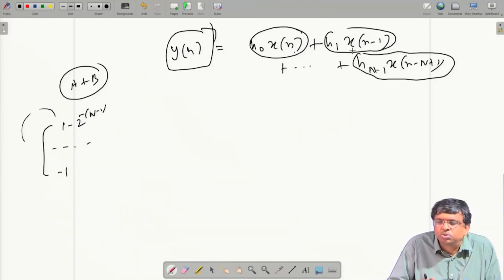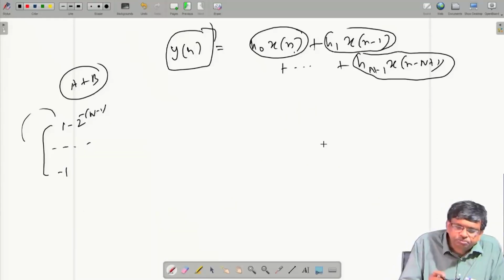This is a property of the two's complement number system, which is very useful in digital signal processing, because here you come across convolution sums where too many things will be added, or you do a transform, discrete cosine transform or DFT, where again in the summation you have too many things to be added and like that. You are guaranteed to have an overflow free operation result. This is the main advantage.